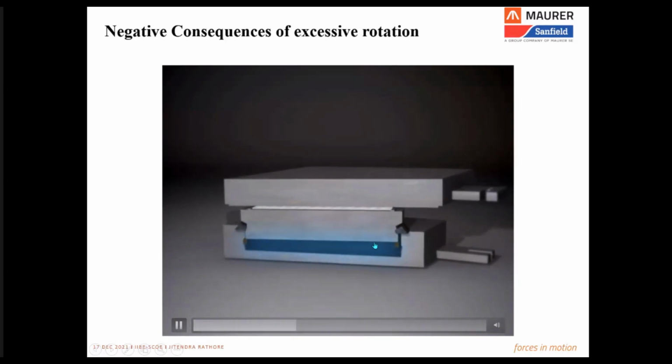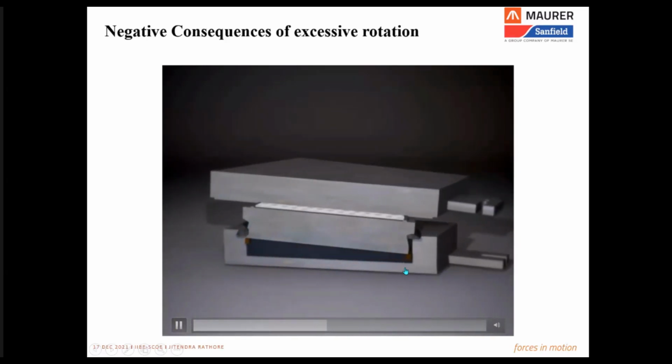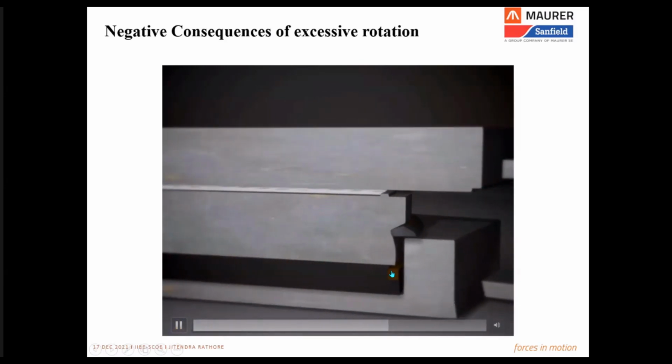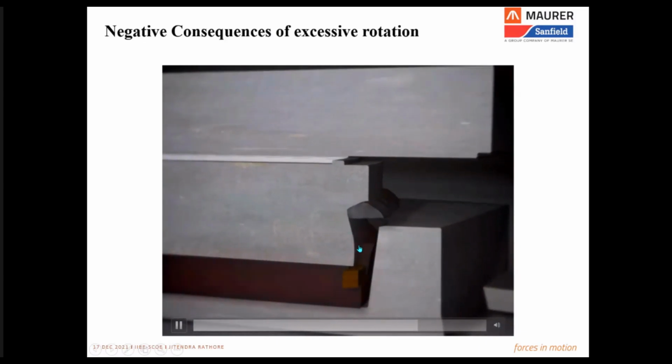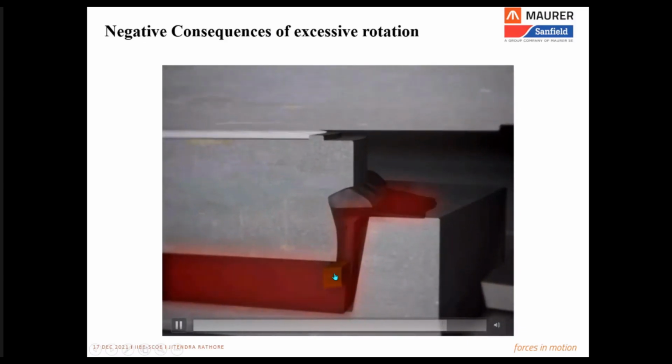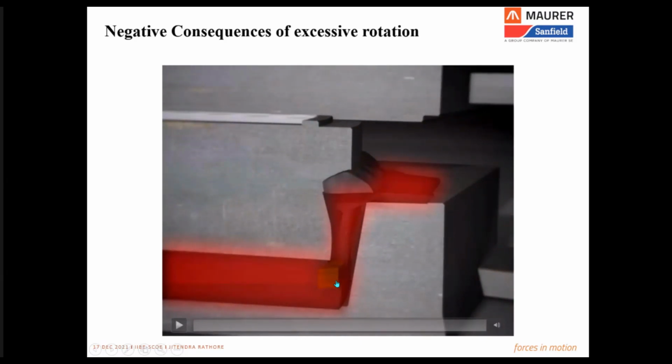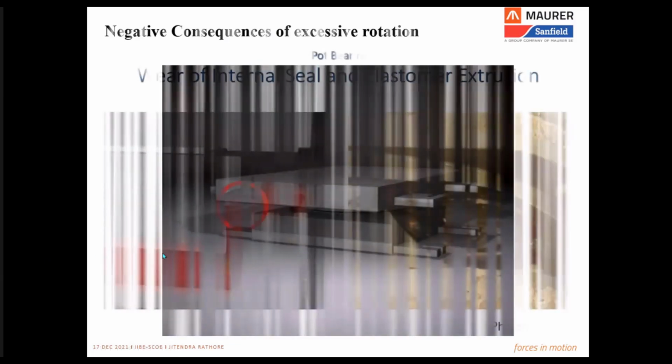So when there is a frequent rotation and higher movement of the sliding material or the sealing rings, it wears over the period of time and it starts oozing out of the elastomer. This also happens when the elastomer is tilted to a greater extent beyond its limit to cover the gap and the effectiveness of the sealing rings is lost, then also the elastomer can ooze out, and therefore it is very much important that the bearings are installed horizontal.